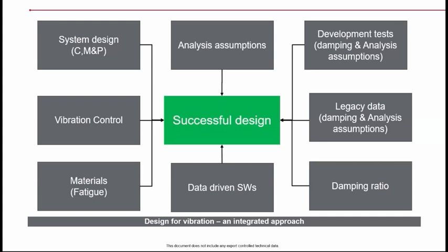Yes. Generally, before going for FRFs correlation, that is response correlation methods, you have frequency response assurance criterion and frequency domain assurance criterion. There are two different methods like that, but they are not so evolved currently to utilize with the software, or otherwise we have to develop our own codes to utilize. However, we can always do harmonic sweep in our analysis, or if it is random vibration analysis, we can take spectral density plots out of our response analysis and overlay them on the test plot. Okay, got it.